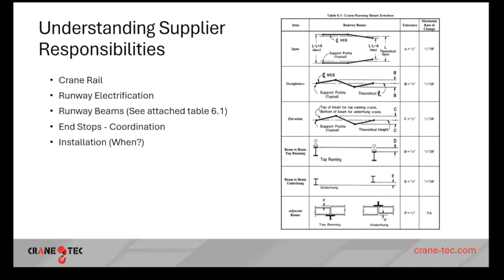From my perspective, I would say obviously deflection is super ultra critical, especially when you get into the heavier crane systems out there. Precision is obviously key. There is not a lot of room for tolerance. You have to be locked in. The deflections are going to drive how we design. So our engineers are going to simply have to look at all things that are going on in the building, environmental loads, coupled with what the actual deflection criteria from the CMAA is. That's all on the table.